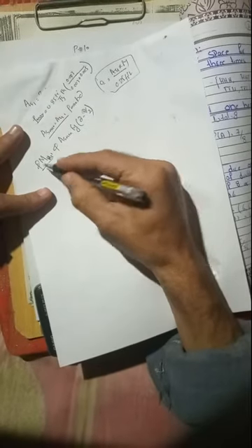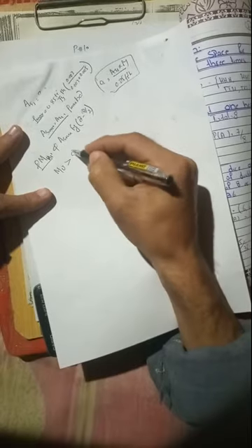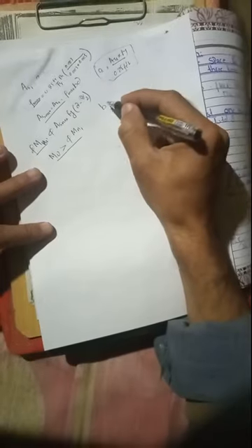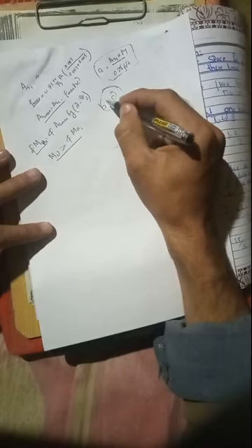Now you have to compare this capacity with Mu. If Mu is greater than this value, Mn1, this means that the section capacity is not enough to support this moment, and we need a doubly reinforced beam analysis. If the architect bounds you not to change the b and d values, these values are fixed. So in that case you have to go for the doubly reinforced beam.